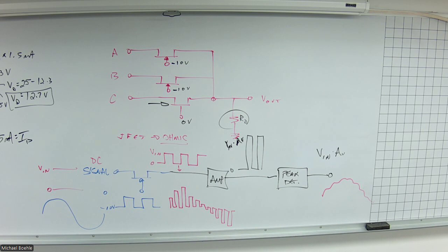Use a JFET amplifier as a buffer amplifier because one of the things we learned about it is it has a very high input impedance and can have a relatively low output impedance. Very similar to what we did with our bipolar junction transistor amplifiers, where different configurations provide a different amount of input and output impedances. The JFET is also good for low noise applications.